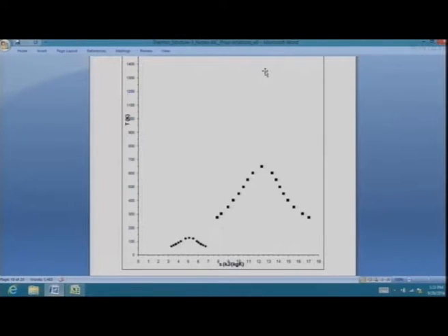So 1400, 1700, 1900 Kelvin, which are now temperatures that we are talking of in combustors and burners, we are far away from this dome, and we can say that look, I'm far away from the critical point. Anything like this, I can quite happily accept that this is ideal gas behavior. In fact, that's what we do for nitrogen. Critical point of nitrogen is 126 Kelvin. We live in 300 Kelvin plus type of a thing. So we are about more than 2.5 times the critical temperature of nitrogen.